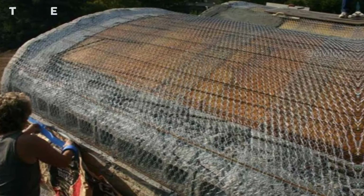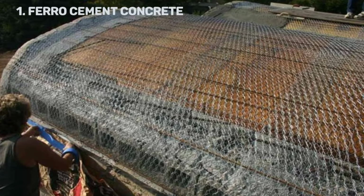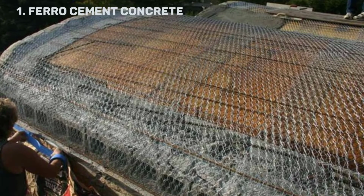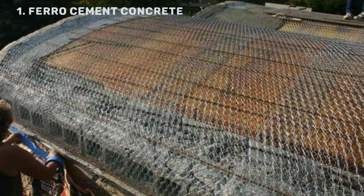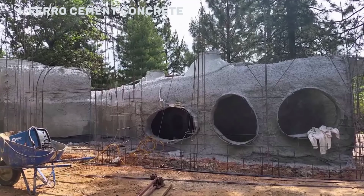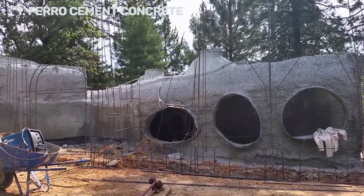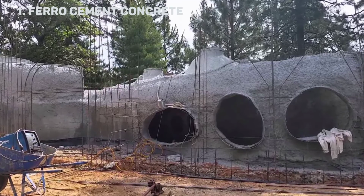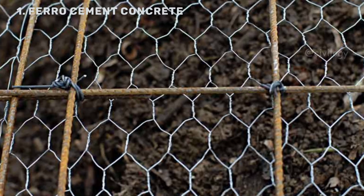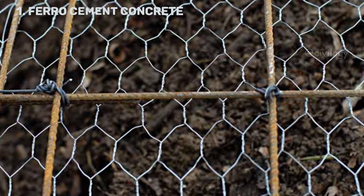And next, ferro cement concrete. Ferro cement concrete should not be confused with fiber concrete. Ferro cement consists of closely spaced wire meshes which are impregnated with a rich mix of cement mortar. The material was developed in 1940 by the Italian architect P.L. Nervi to build a large number of pleasing structural forms. The steel content of this concrete will be as high as 300 to 500 kg per meter cube of the mortar. As the material consists of a large percentage of steel, it has high ductility and tensile strength.